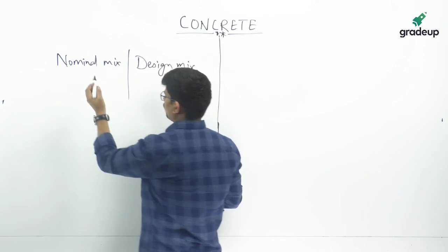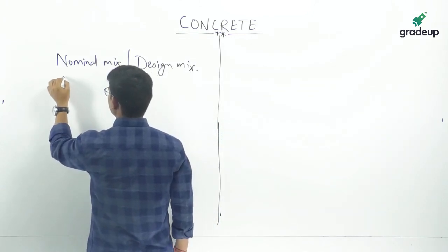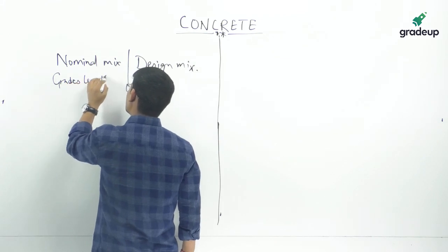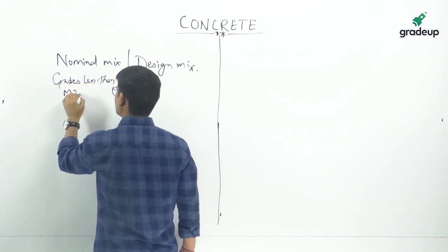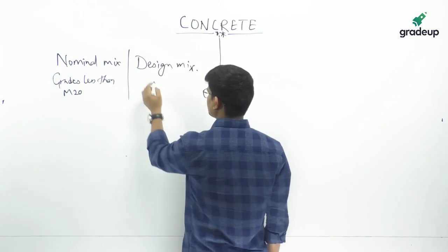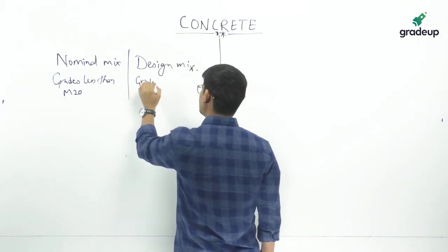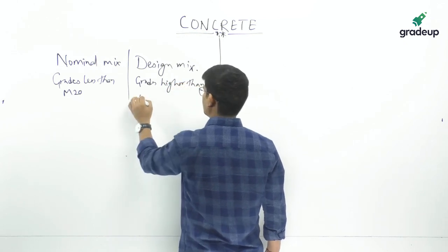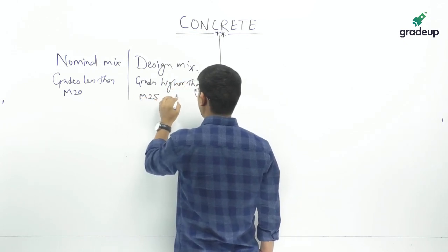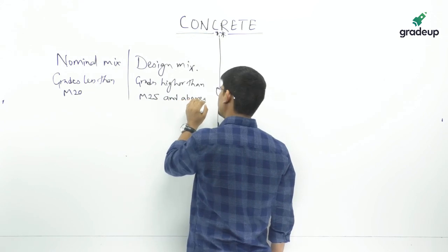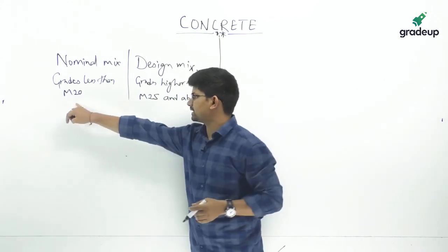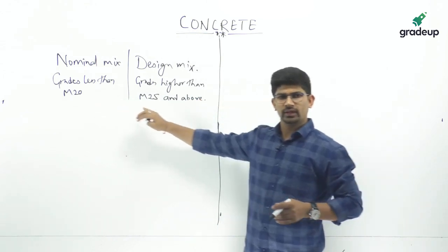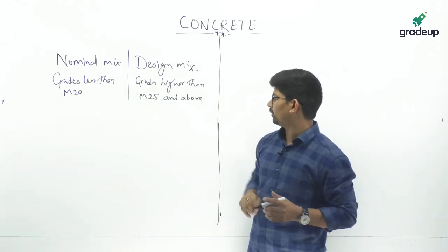Nominal mix is generally for grades less than M20, including M20. Design mix is for grades M25 and above.